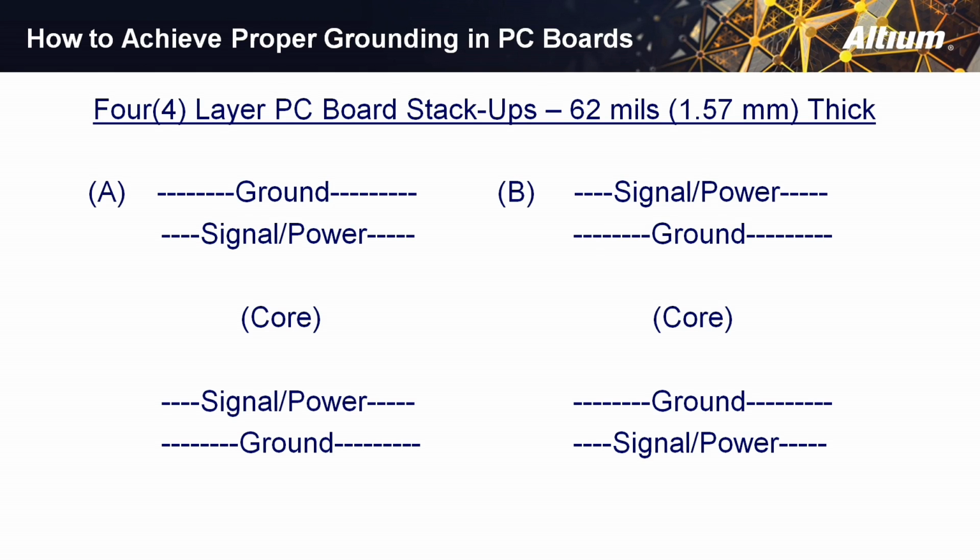When we moved the signals to the inner layers, there was a lot of area on the outer surface of the board where we could pour ground. And when we moved the signals to the inner layer, we made sure that they were sitting under that ground on layers 2 and 3. We then poured the open areas on layers 2 and 3 with power so that we had power on layers 2 and 3 referencing ground on 1 and 4.